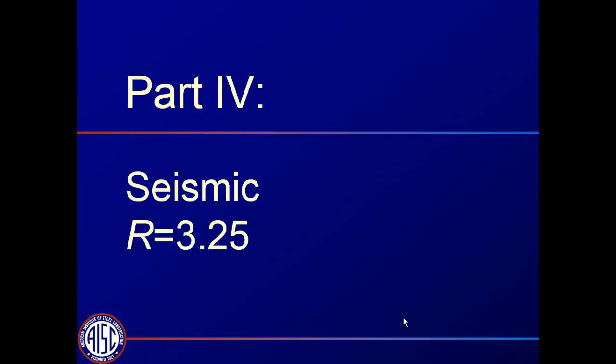The first question is in regards to the omega factor. Does omega apply to the column in the brace/collector connections? So the question is, does omega apply to the column? For the R equals 3 system, the column is not required to be designed for omega.